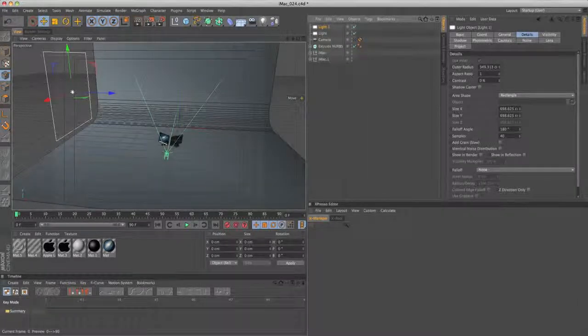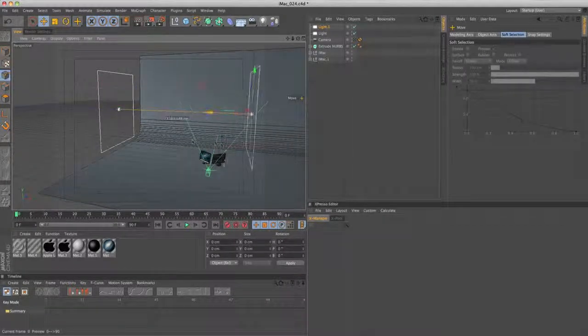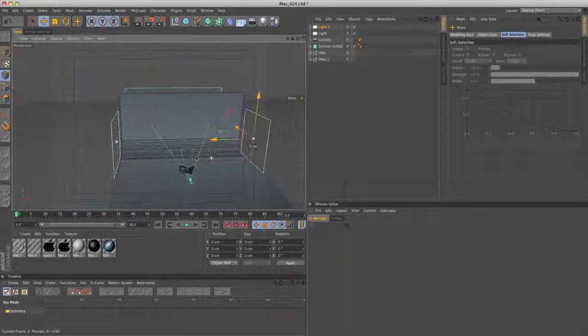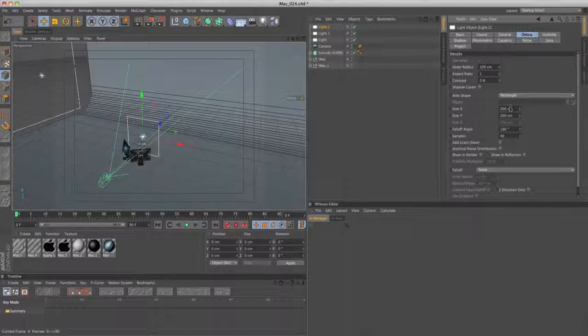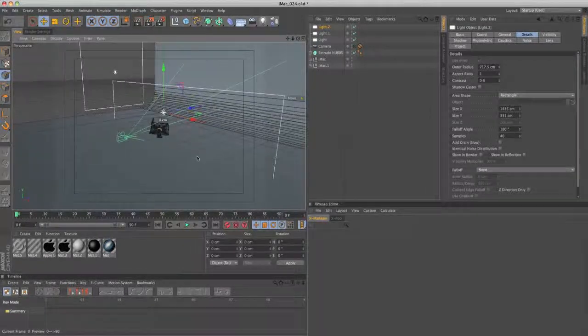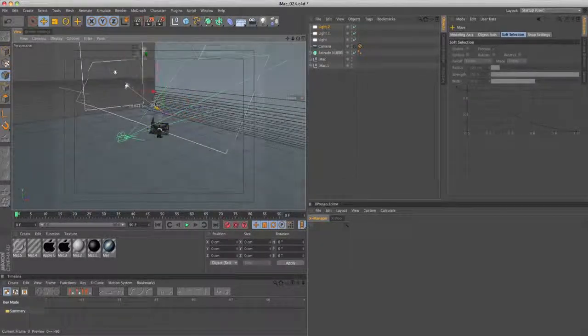and then we're going to copy and paste that light and rotate it 180 degrees. And then we're going to move this light over to the other side. And then we're going to come up to the light tab again and select area light. And then come into the details of this light and change the size X and size Y. And then we're going to rotate this at a 40 degree angle and then just move it upwards.